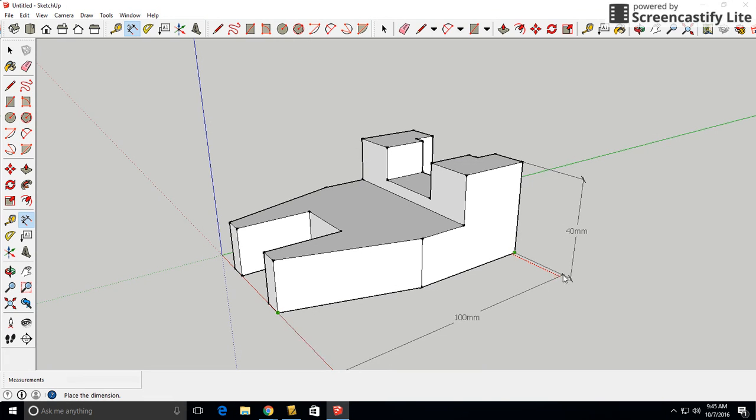to the back point. Now I'm going to drag that dimension mark so that it lines up with the overall height dimension, because when possible, you want these dimension marks to line up. The leader lines should end in the same point. All right, now there's one more dimension along this edge, and that's the 50 millimeter dimension for the front jaw. And if we're in the dimension tool, we can click on the endpoint there.